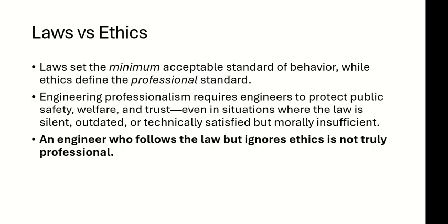So the law may say that if you are using steel structure in Bahrain, these are the standards. But you know, if the structure is sea facing, then the steel may have more losses, greater losses, and faster losses as compared to when the structure is not sea facing. So should you just stop at the law? No. Then you go ahead and you do something more, which is your ethical and professional responsibility.